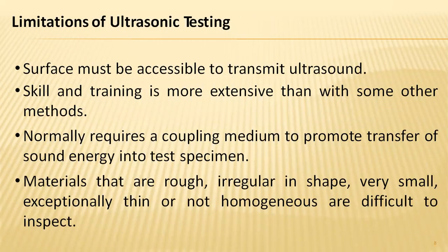Coming to some of the limitations, as we have already discussed, when compared to other techniques it has a wide range of depth of penetration, but even so it is limited to particular levels of penetration. Hence, the limitations here are that the surface must be accessible to transmit the ultrasound.